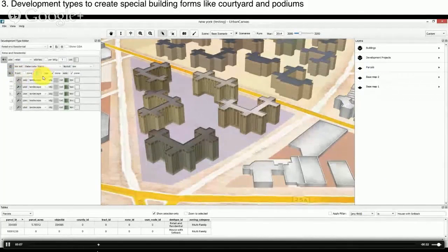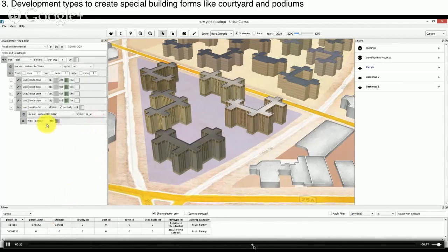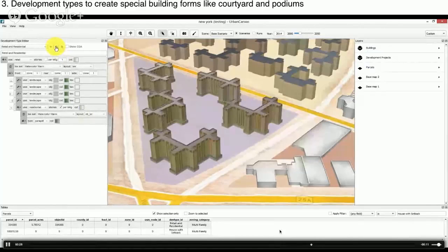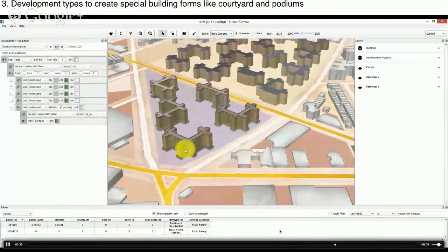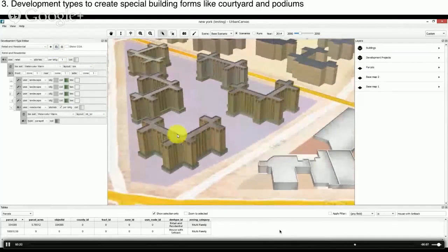So again, I split the upper surface. I extrude it to a single story, the retail. And then the roof of the retail I split, and I give the front, rear, and side setback values as 1 meter. So that's the setback that will be applied to the upper level housing. And then I give the textures and colors as I desire. And these are the HSV ranges that I provide. And as I save it, I'll instantly see the results on the parcel I applied it to, and you see a meter setback on the upper levels here.